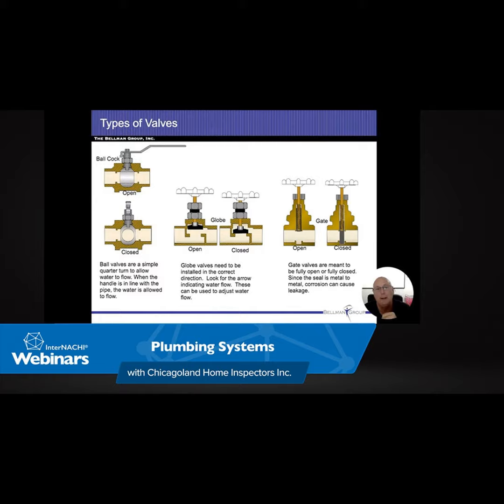But in residential buildings, typically we're going to be 3 stories tall at the most. Rarely are we going to be 4 stories tall. And usually you lose on average 5 psi per floor. The exact number is you lose 1 pound for every 2.2 feet of elevation. So every 10 feet is what we're rounding up to be 1 floor of elevation. So we just round it to 5 psi for every floor.